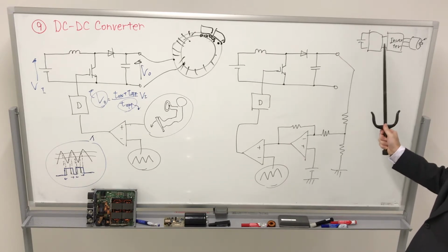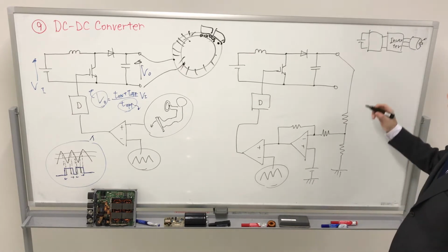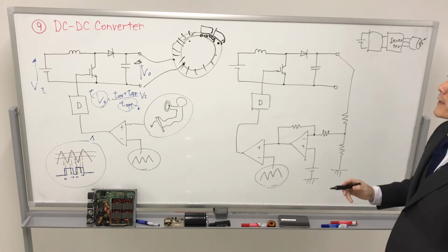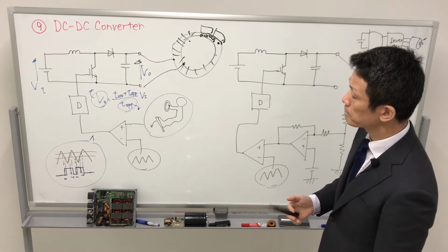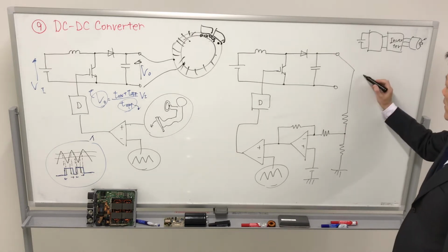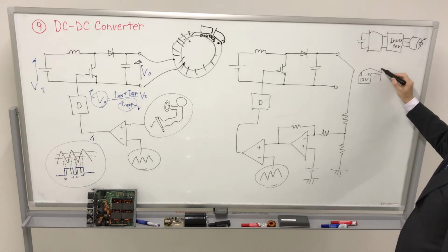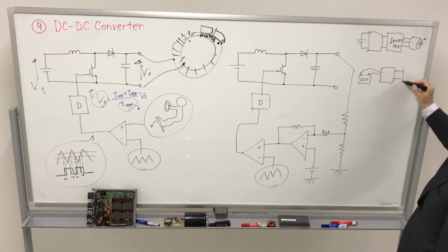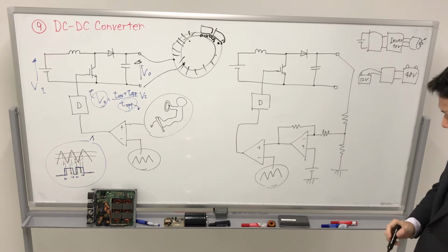In the case of 48 volt systems, the Mercedes S class and C class and Audi's SQ7 have a 12 volt lead acid battery, a DC-DC converter and a 48 volt lithium battery.